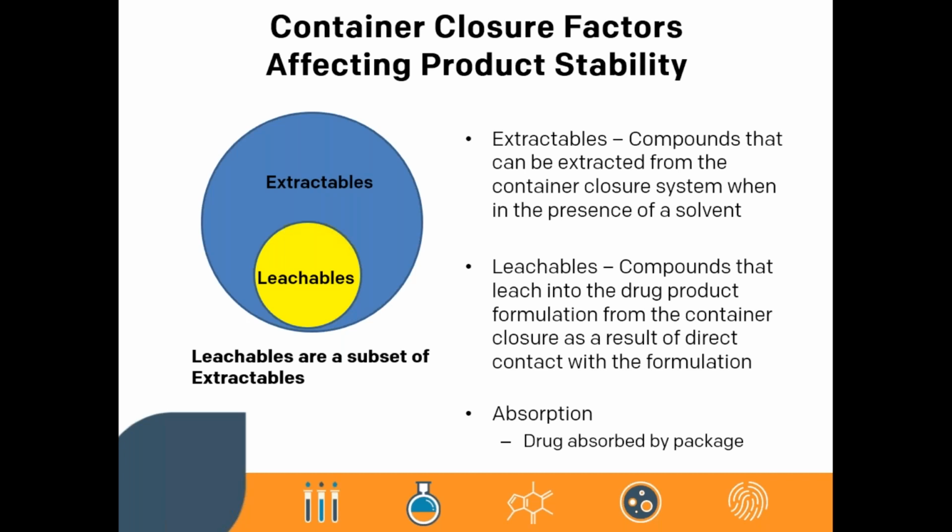Extractables and leachables are an important issue. There's a lot of interest in that container closure, and you can see what extractables and leachables are. Really, leachables are products that are leached into that drug product from the container itself, and extractables are compounds that might be coming from the container closure when in contact with the solvent that's placed inside that container, and those are an important aspect to look at as well.